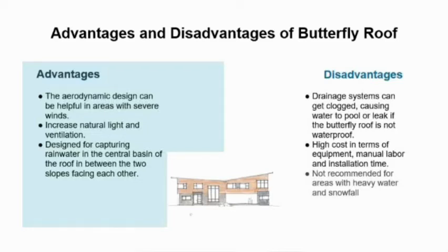Then, the roofing style allows the use of clerestory windows. The size of the windows allows the entry of natural lighting and enhances proper ventilation to the interior space. Then, the direction of slope on both gables allows maximum collection of rainwater, which benefits those who harvest rainwater.